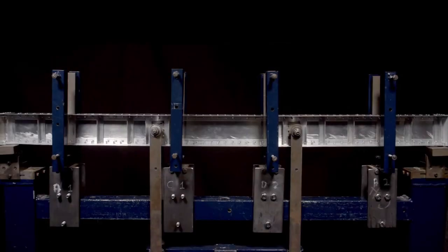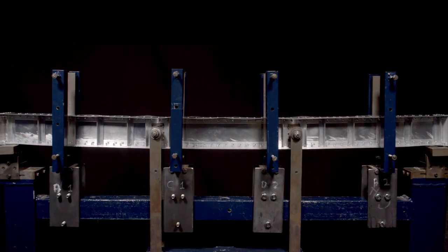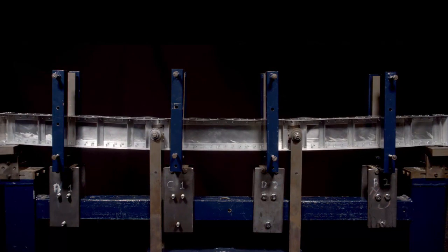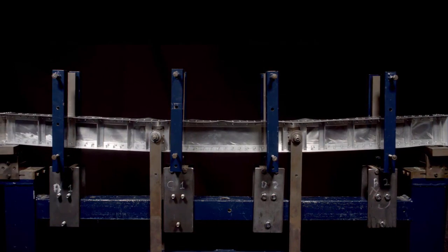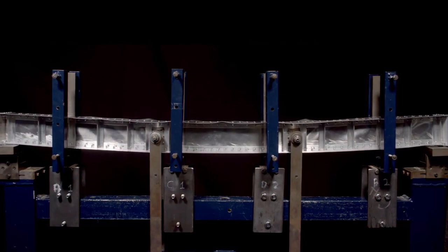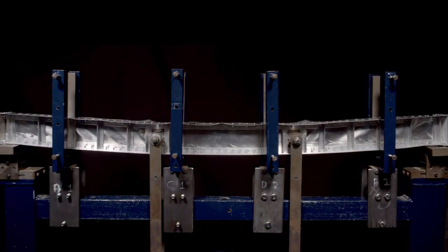The testing rig is now starting to apply a pair of equal vertical loads to the central third of the beam. As the loading is applied, the beam begins to sag. The top flange is effectively under pure compression. Once the compressive stress exceeds the flange critical stress, buckling of the flange will occur. This can be seen as ripples along the length of the flange. These ripples reduce the beam stiffness and deflections become higher.